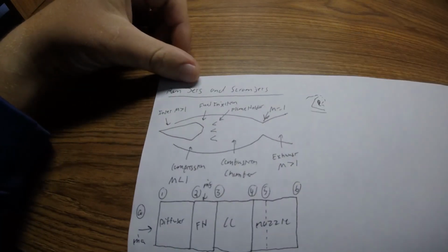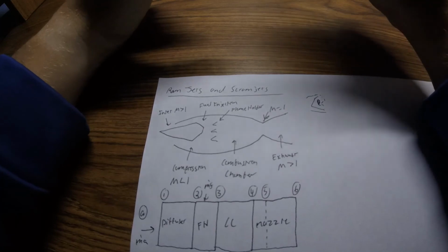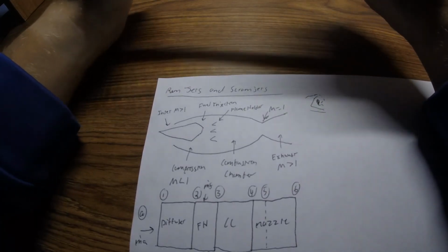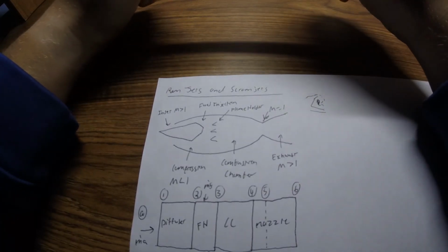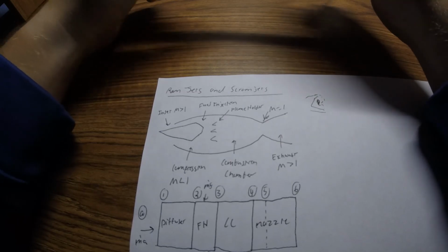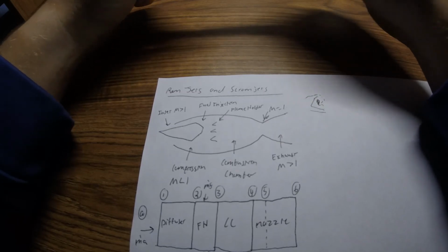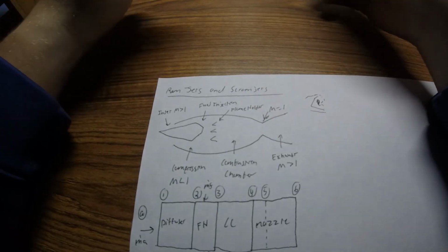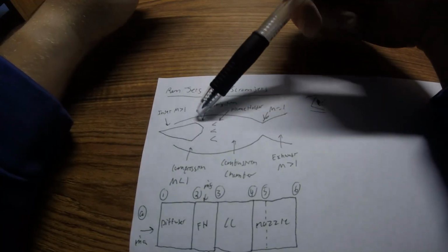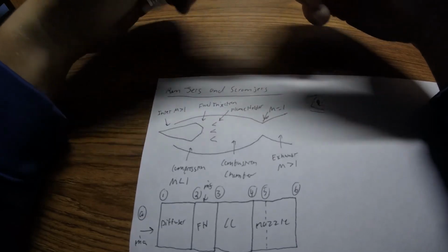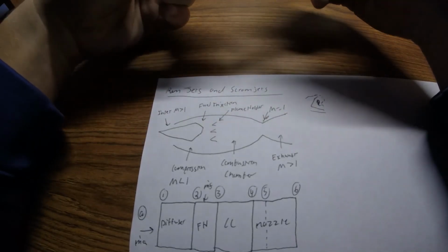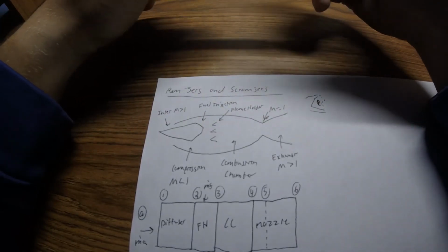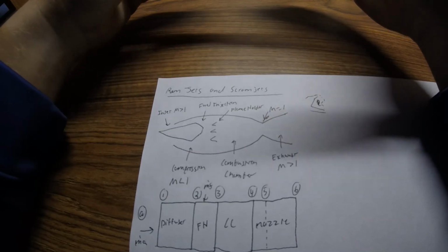Therefore, ramjets are most commonly used on something like a missile, where it can use a rocket engine, a solid propellant or a liquid propellant rocket engine, to create the thrust to start, and then can kick over to a ramjet to extend the range, and ultimately use less fuel than a strict rocket would.